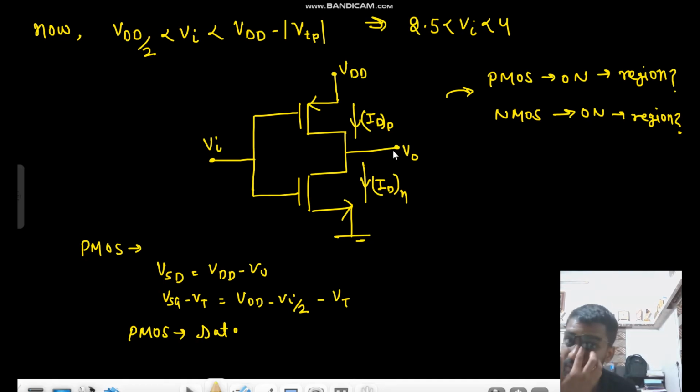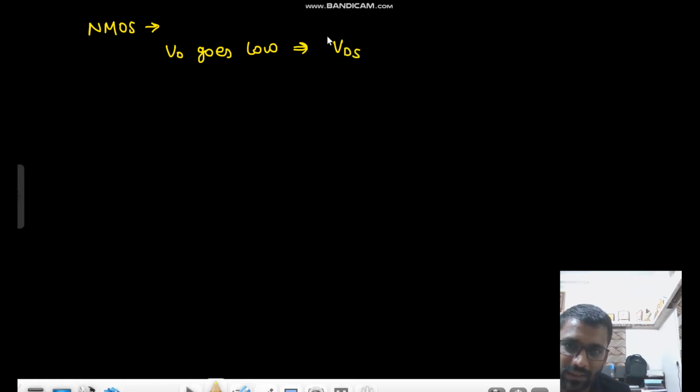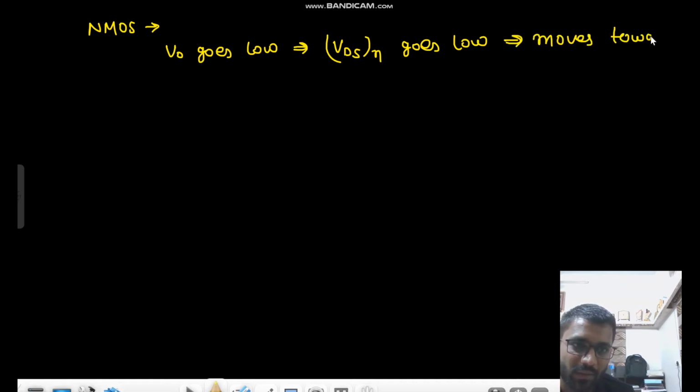Now your V naught is decreasing. That means your VDS of N is going low. Talking about NMOS, V naught goes low. That means your VDS of N goes low. That means it moves towards what? Linear region.